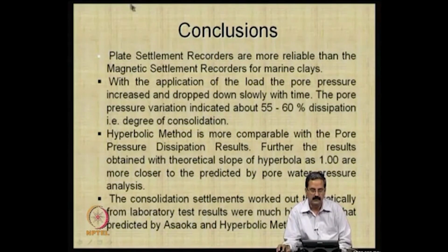So, what they observed was that the plate settlement recorders are more reliable than the magnetic settlement recorders for marine clays. With the application of the load, the pore pressure increased and dropped down slowly with time.